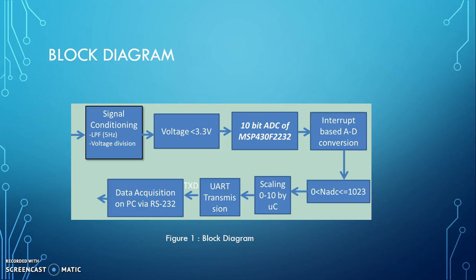For data acquisition purpose, I used Arduino to collect data. Later, Arduino serial transmission is picked up by a serial port application named CoolTerm, which I will show later, which helps me produce a text file with the data it finds in the connected serial port. My MATLAB code reads this text file and plots the data on the computer screen.